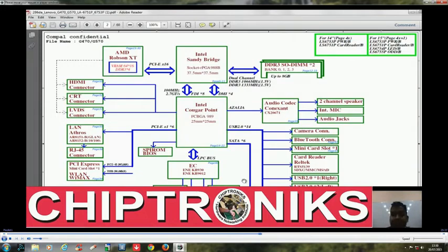When I'm explaining Lenovo G570, the concept and the signal names are common to all i3 based laptops. When I'm discussing HP DB2000, the concepts are very similar in all kinds of dual core based laptops. Maybe the position may differ, but the signal name would always remain constant.